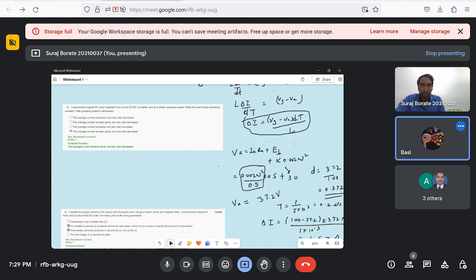So we need a way to reduce the voltage from 12 volt to let's say 5 volt, and then supply this to the Arduino. If you directly supply 12 volt, it will destroy the Arduino, or any microcontroller or electronics. For the motor you can provide 12 volts directly to the motor driver. That is why we need this buck converter. Sometimes we also need a boost converter, which increases the voltage. Okay, that's all about the converter.